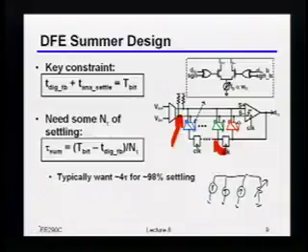Not from the GM, just from the fact that, as an example, remember, there's some data pattern in the shift register here, right? Yeah. So let's say I had 20 taps. It could be that I have 19 ones and 1 zero, and then that one zero I flip from being a 0 to a 1. The voltage impact of that would be very different than having 19 zeros and flipping the last tap from a 0 to a 1. Okay. Right? That's the nonlinearity I'm referring to.